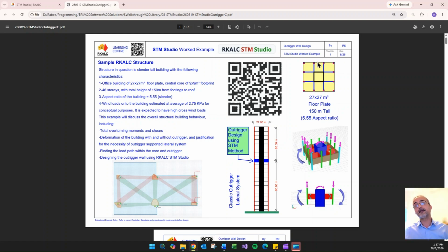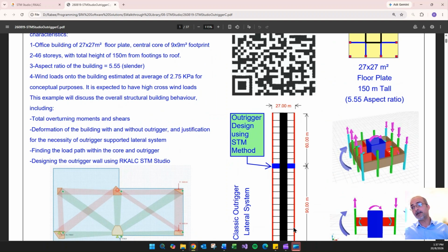this nature. The outrigger system itself is a connection between the central core and the external columns, where you can increase the lever arm of your core essentially and add muscles to your system, where you can reduce the lateral deformation and the bending moment by extension to the core and spread it to the columns.